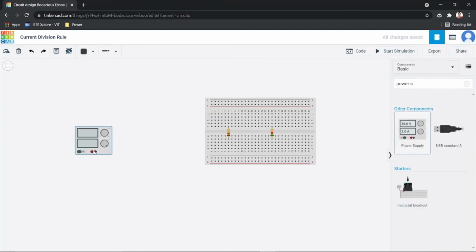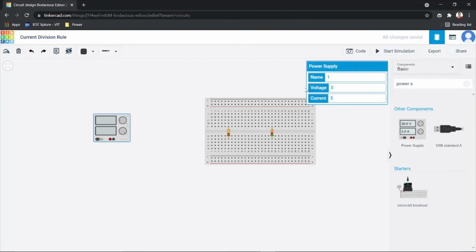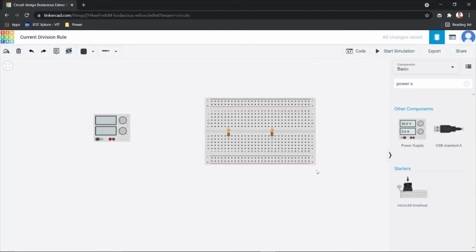So that we have taken, and we will set it as PS 5 volt and 1 amp current. That is the minimum that you can set here. Afterwards, it will change it to the total current in the circuit. Because once you make the connections and start the simulation, all the voltage drops and according to Ohm's law, the final current through the circuit can be estimated. So that is being done actually in the simulation also.